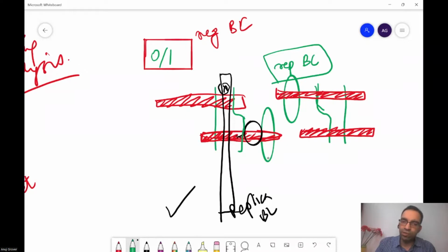You know that there is some VDD over here. There is a VDD supply here. But you do not know how to connect it to that supply yet, because you cannot simply short. If you short, then the capacitance on this particular bit line would start to appear as different from another bit line. So what is typically done is, one thing is, okay, so there is a long contact over here.